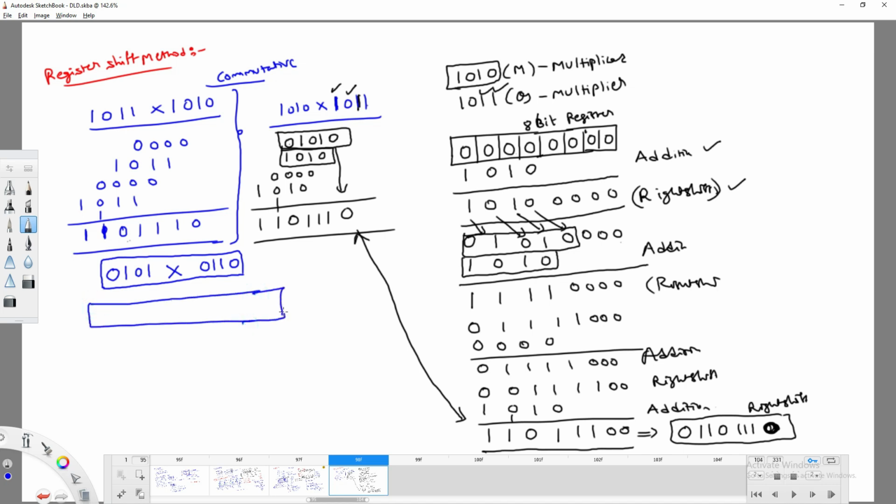So as the multiplicand contains 4 bits and the multiplier contains 4 bits, your result will get a maximum of 8 bits, right? So 1 2 3 4 5 6 7 and 8. Now, when you are performing multiplication with 0, simply add that number of zeros. You are going to get 4 zeros followed by again 4 zeros. Now after that you have to perform addition.